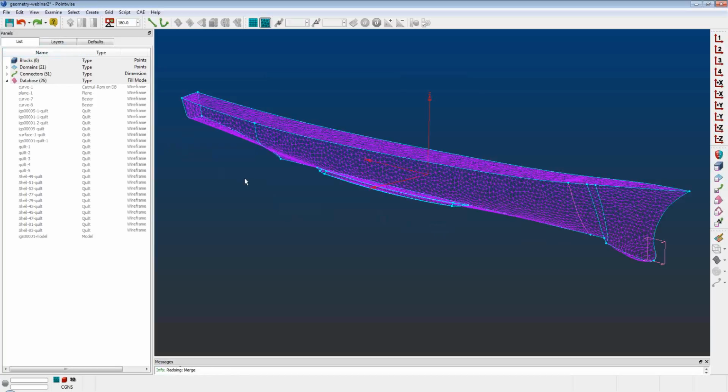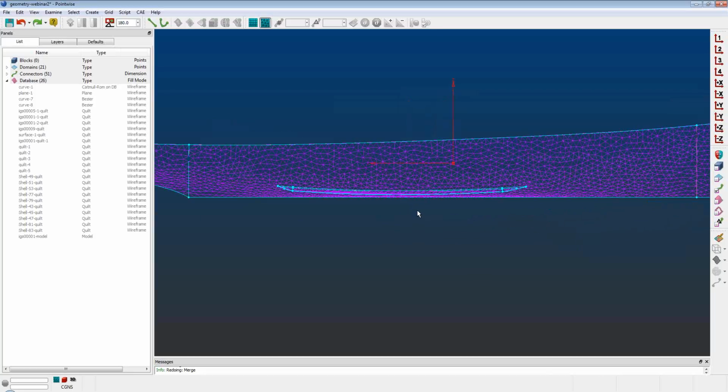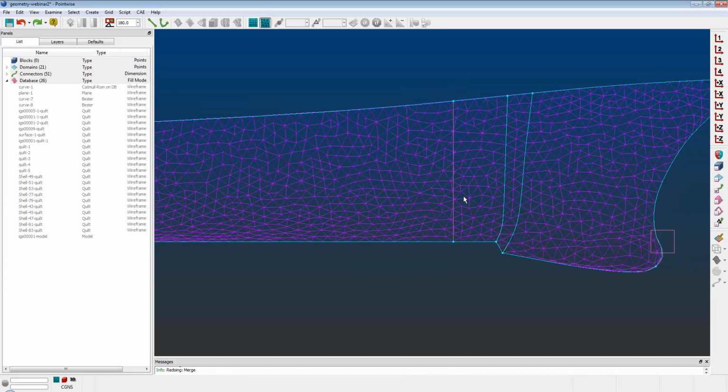Okay. So you remember in the center of the fuselage, where you join that forward portion? Right about here, yeah, right there. On the top you have a connector, basically two connectors. So when you join those surfaces and mesh over them, it retains those connectors. Is there a way, if you know that you want to join two surfaces, that you can also join those two pieces into one connector in one step? Same with the bottom.